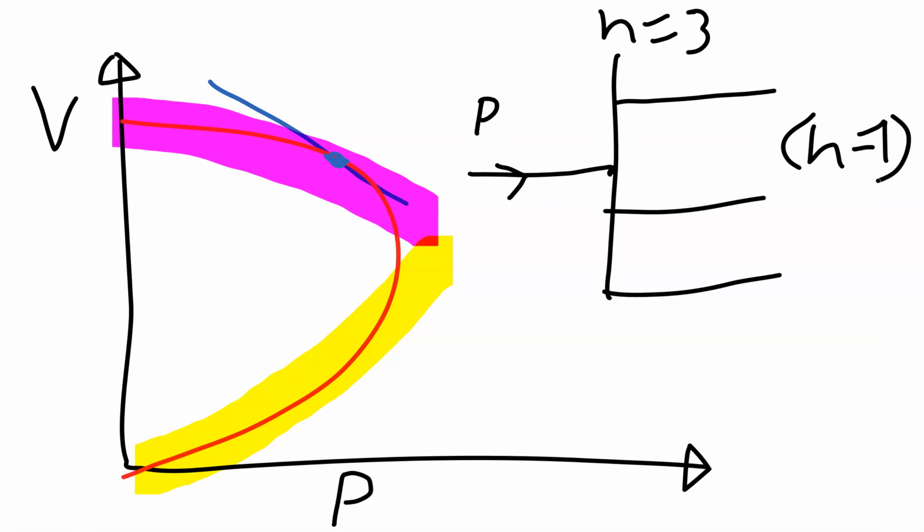That means even though one of these lines goes out of service, the rest of the lines should carry the load flow. Sometimes they want even more safety in the system, and they should probably have n-2. That is also sometimes checked. So this is also a very important criteria.